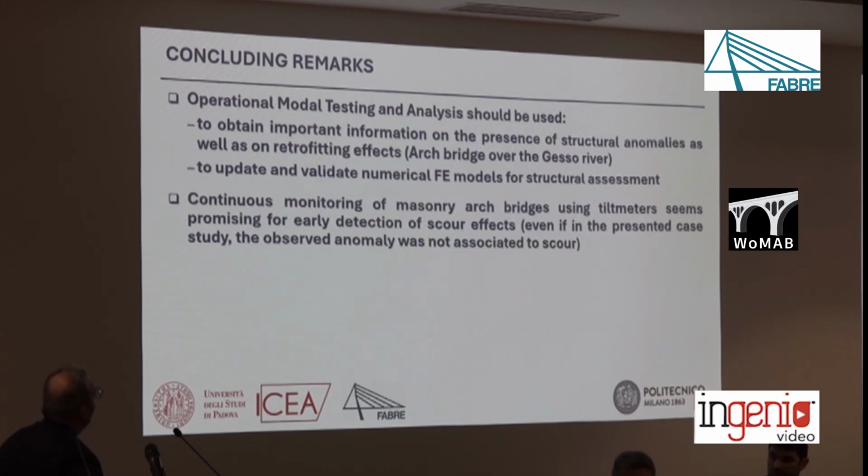But as we all know, operational modal analysis is a key step for updating and validating numerical finite element models for structural assessment. In addition, the continuous monitoring of masonry arch bridges using tilt meters seems promising for early detection also of scour effects, generally for the detection of structural health, even if in the presented case study the observed anomaly was not associated with scour.